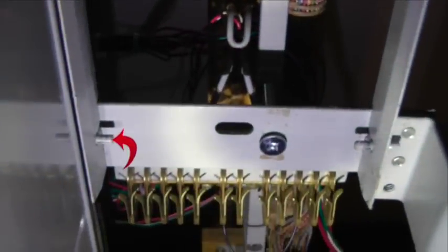On the sides of the switch base are 2 pairs of bayonet-style mounting slots, an upper pair and a lower pair. What we're looking at here is the lower pair. On the connector mounting shelf there are 2 pairs of mounting pins, an upper pair and a lower pair. It is over these pins that the bayonet slots slide to mount the switch firmly into position.